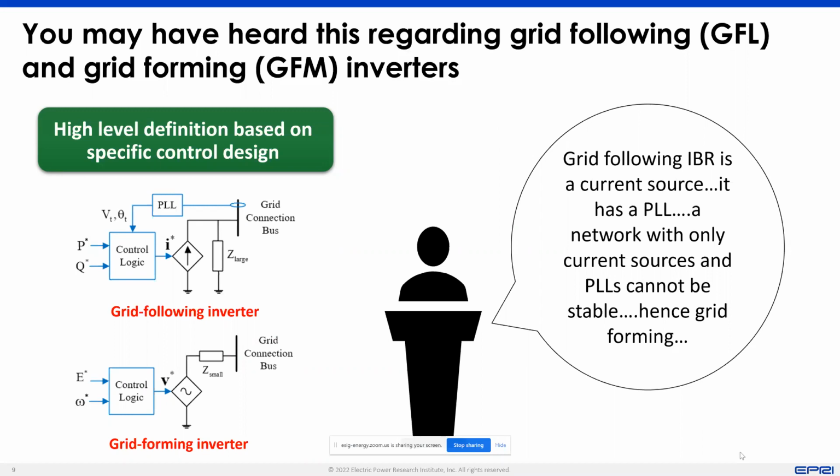So the reason why a voltage source inverter is treated as a current source is because of how it strictly controls its current, or tries to control its current, when a disturbance occurs. Which means that if you don't change the amount of current being injected into the network, or you treat that current injection to be nearly constant in the few instances after a disturbance occurs, then that's what gives it its name as a current source.